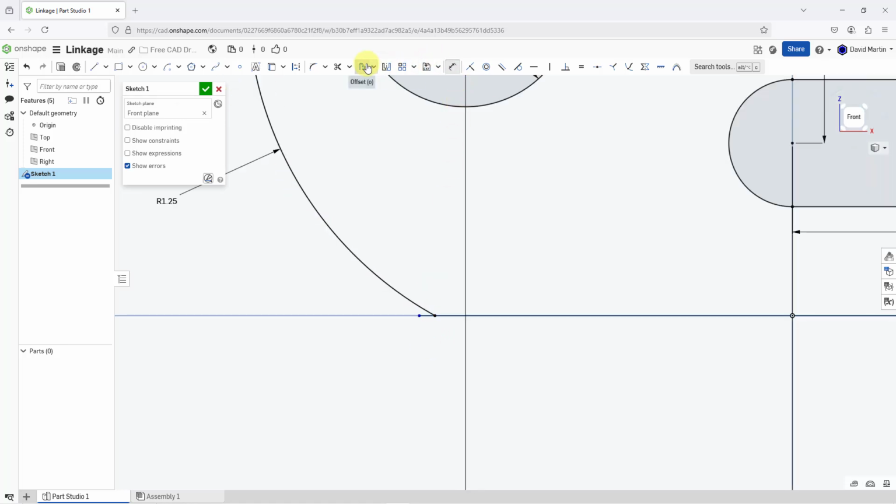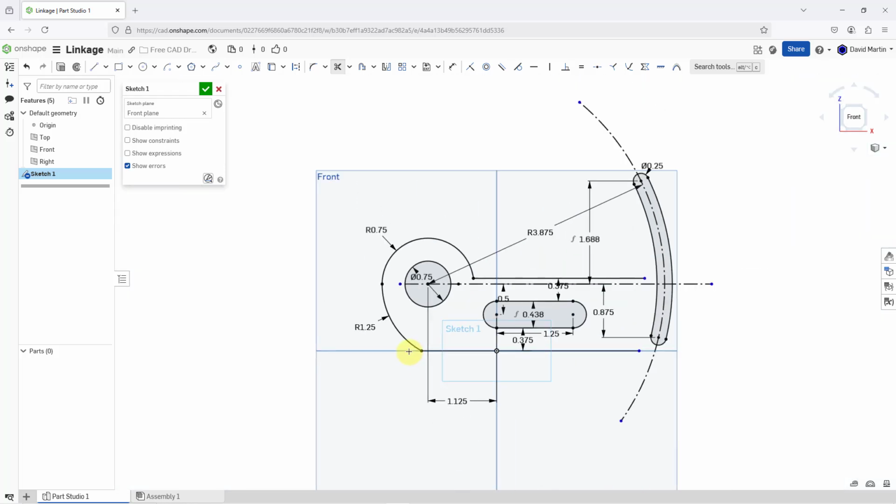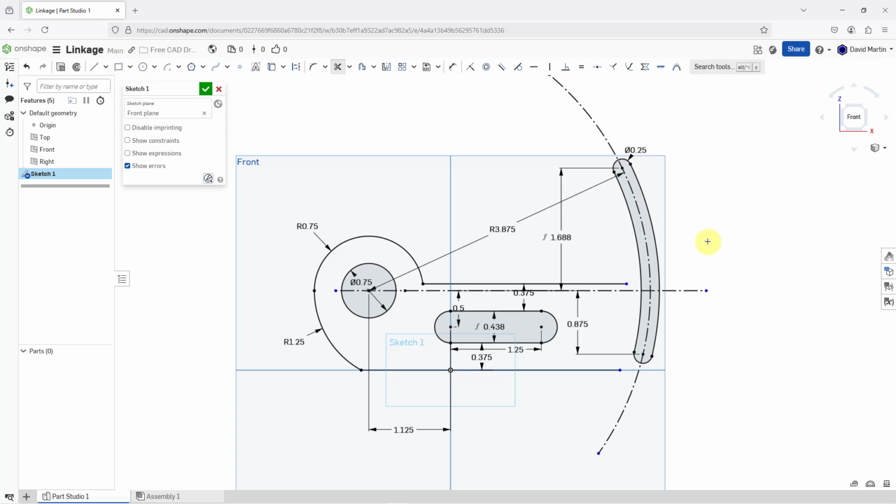So I'm going to trim away that entity. Where are you, scissors? There we go. Let me use this and got rid of that, got rid of that endpoint. Okay, so that is what I'm going to use over on the left-hand side. I'll take care of that sharp corner right there in a moment, because again, the intent is just a little unclear to me. All right, I don't think I need my planes displayed anymore, so I'll use the keyboard shortcut P to turn them off.